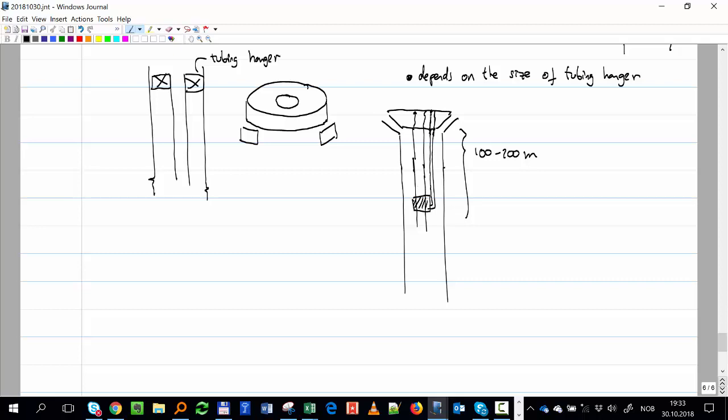The moment something happens, let's say an accident happens here at the top, a rig or a machine hits and cuts the communication of that hydraulic line, that valve is going to automatically close, because it's a fail-safe mechanism. What happens if a crane comes, or a hurricane happens, or something knocks out the Christmas tree? The well will be producing without control.